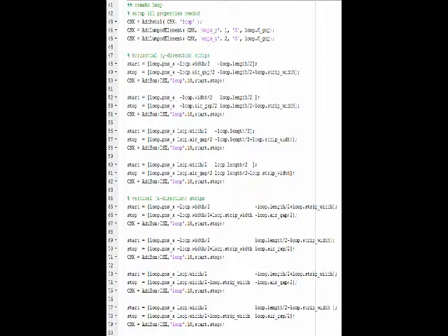Then we create the CSX structure. To set up the CSX CAD geometry, we use the function init CSX, just like the function init FDTD in the previous step. We create the loop and set up all properties needed. In CSX, we then create a metal, taking loop as the parameter, therefore our loop is made up of metal. And then we add a lumped element, and we create another lumped element taking 1 and 2 as difference.